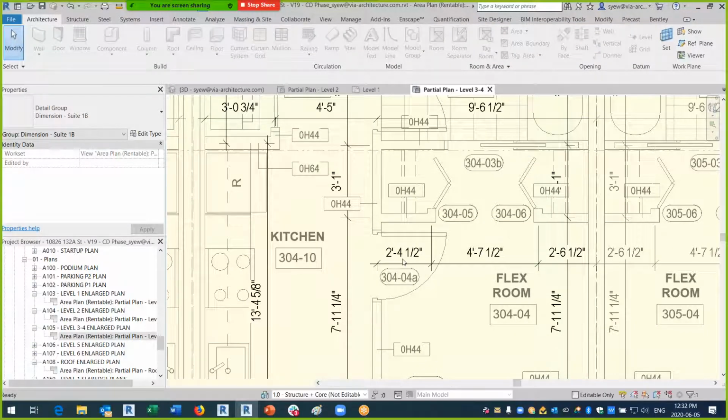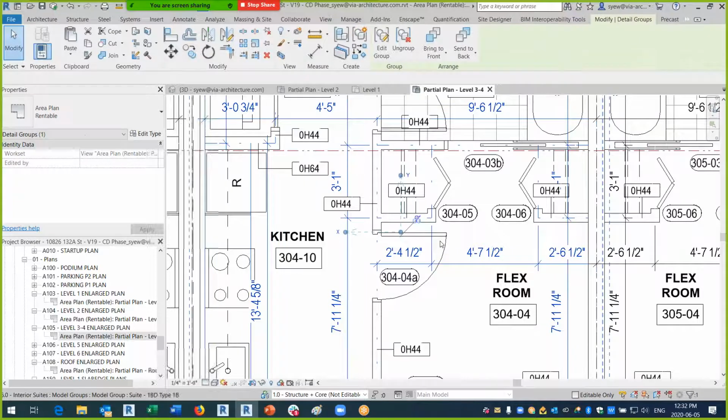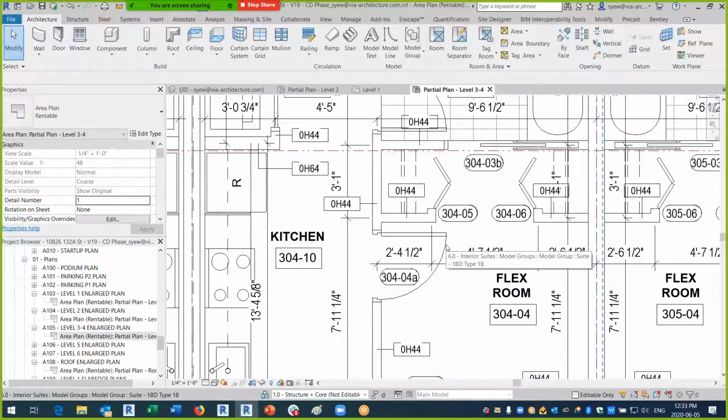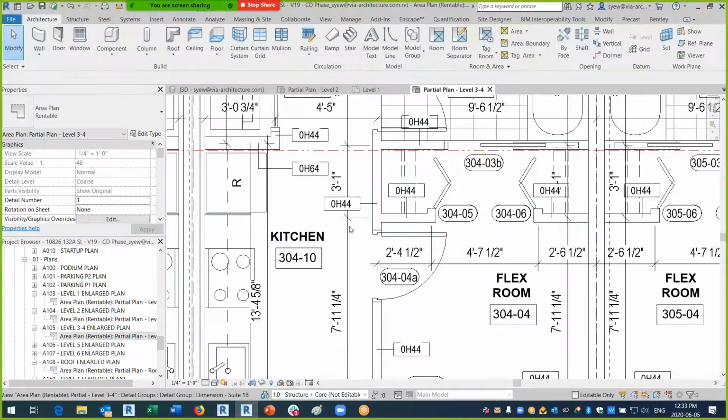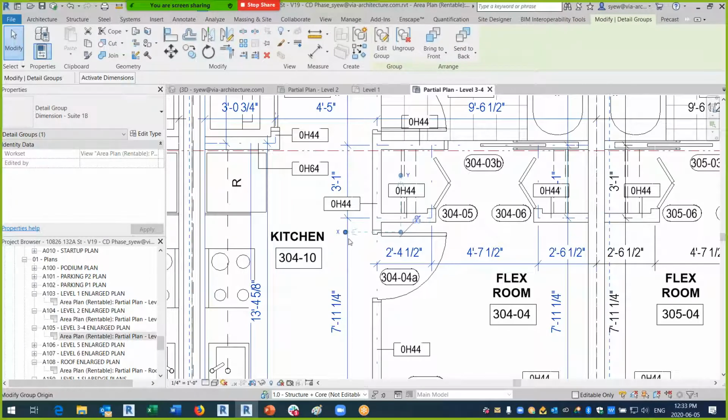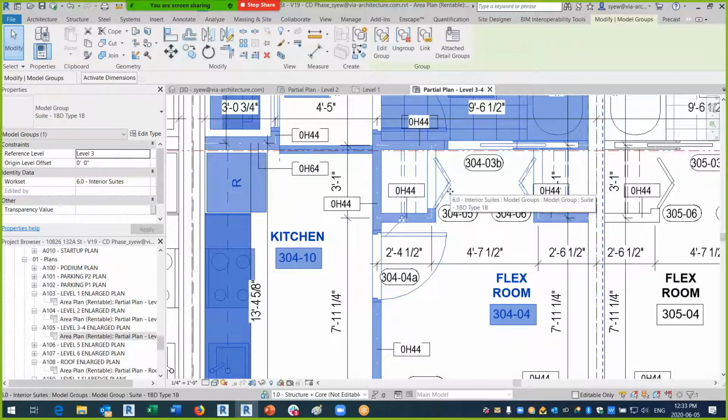The reason why I like to do this is because sometimes people would go in there, modify the units, and sometimes this object moves and you don't know who did it. I have a backup plan where the detail lines become kind of like my object that doesn't get moved. So you can tell QAQC what's been moved and what's not been moved. Nobody knows that I did this, right? So you can check one versus the other. If someone actually moves certain things, then you know that someone moved it.